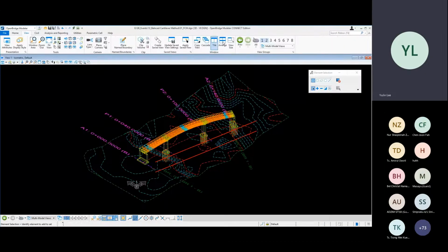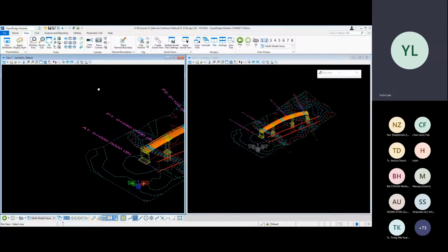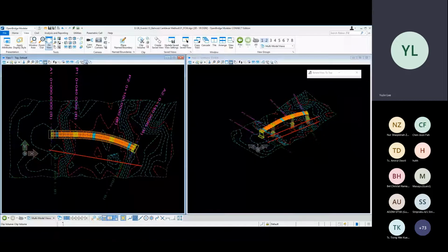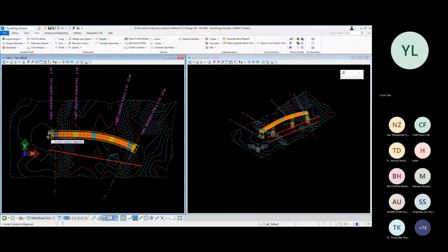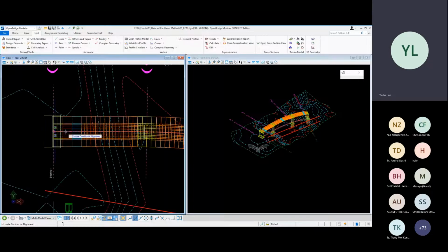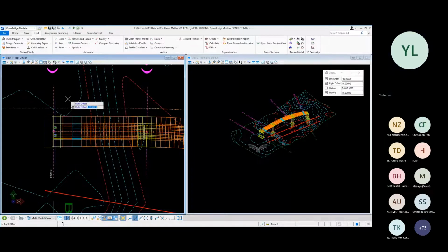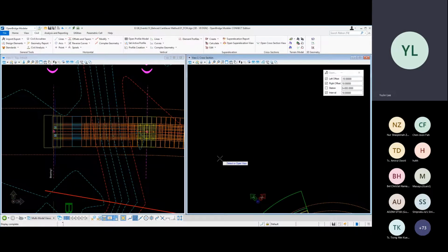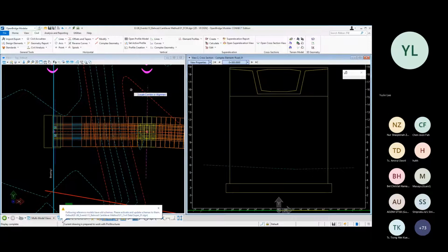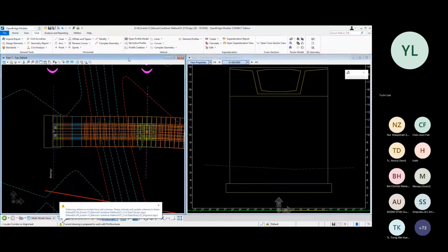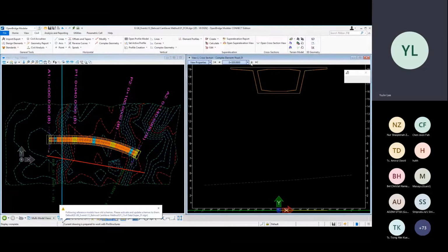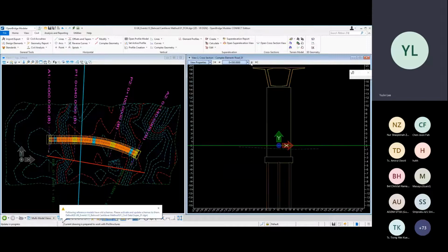And in this step I'm going to explain how to define super elevation using a reference drawing that was generated from OpenRoads Designer. And specify the left and right boundary and select a start station and step spacing to produce a 2D cut drawing. And verifying the 2D cut drawing, you can confirm that the superstructure didn't define any segment.